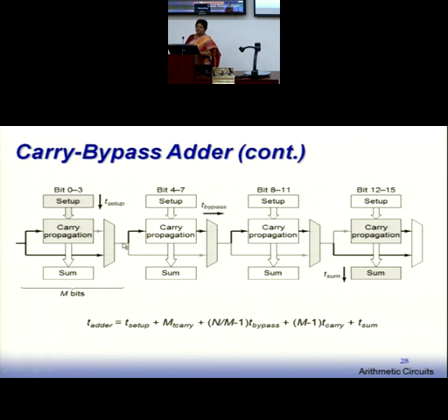That will be your C3, which is going as input to the next 4 bit block. So can you see, by this time, instead of a 4 bit block, I could have made it a 5 bit block. Because my first block is taking the normal 4 bit delay, or normal 1 step delay, plus extra additional delay to generate C3. During that additional delay I can make my next block carry 1 extra bit.